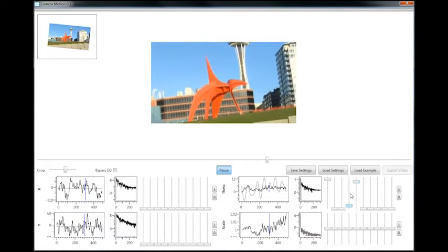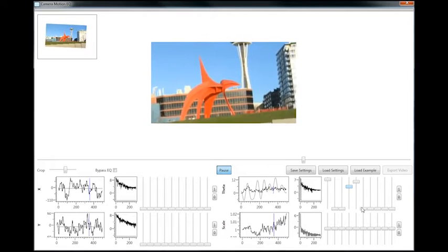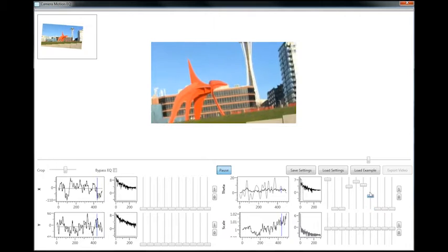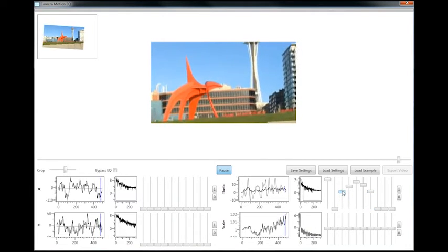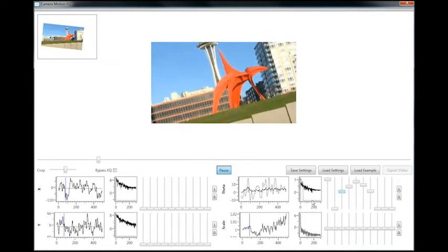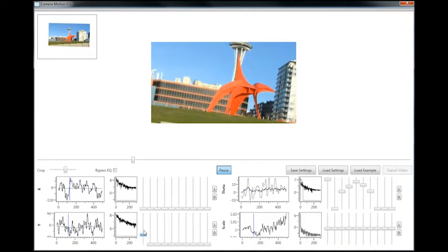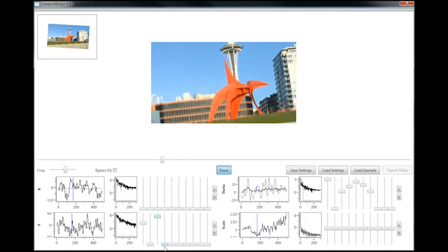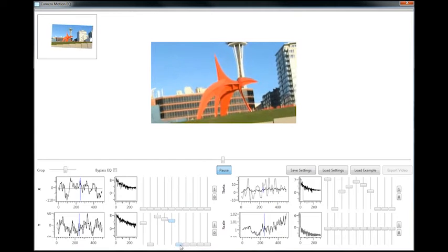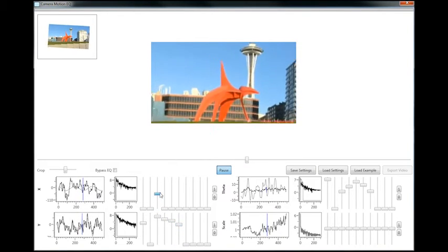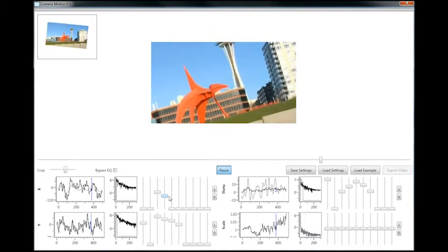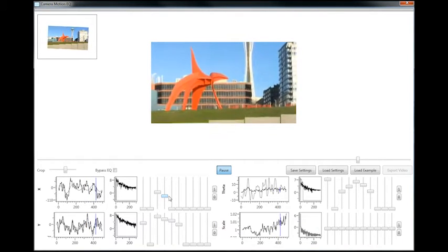By increasing the lower frequencies in the roll channel, the result appears to swim, giving a rolling seas or drunken walk feel. Adding back in some of the X and Y translation results in the desired effect. These settings can be saved as a style for use in other videos.